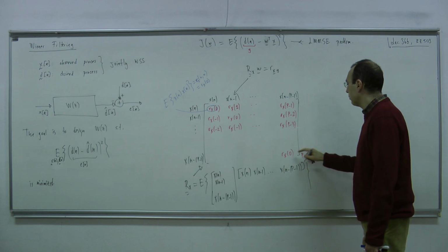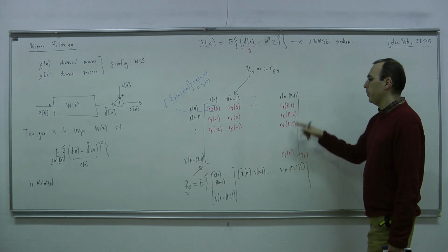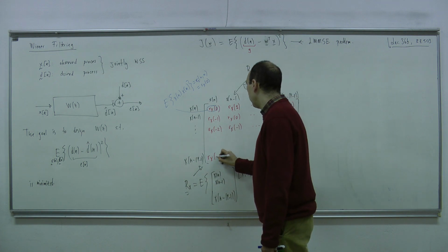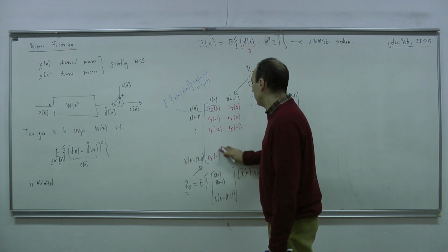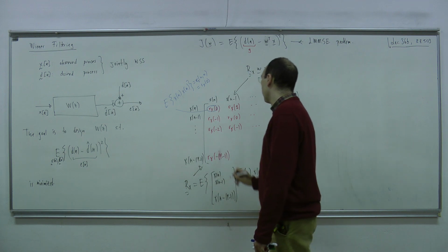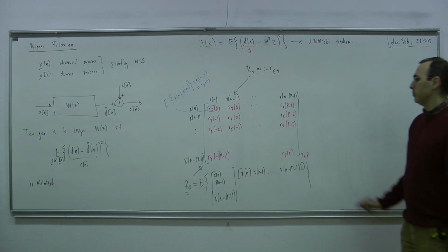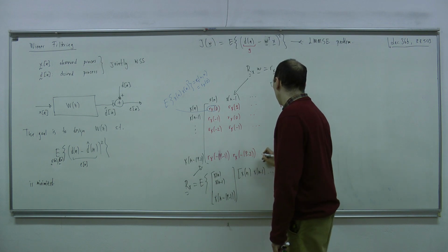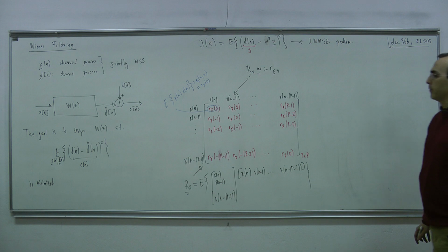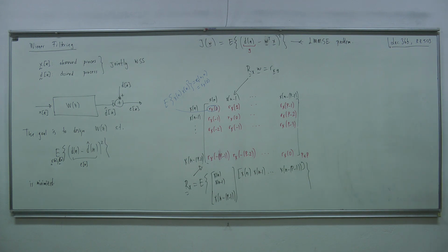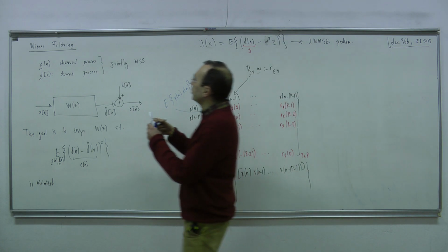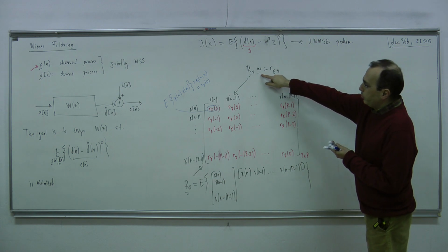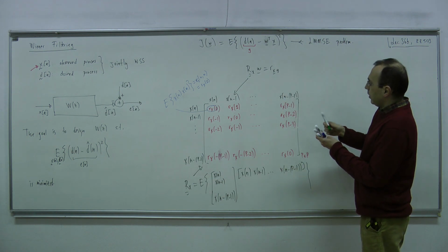So this is a p by p matrix, am I right? This has p over here. Then this is R_x of minus p plus 1, and it goes like this. So this is a p by p matrix that we write from the autocorrelation information of this x(n) process. Very good. Now how about this w? W is the unknown vector, no problems with that. Now how about the other one?